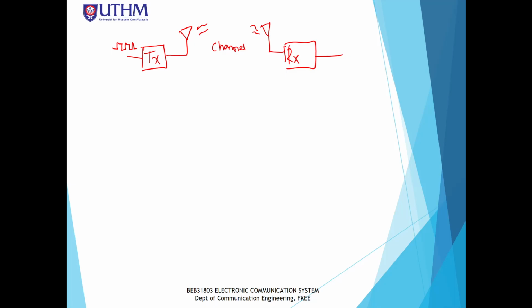So what we do is modulate with an analog carrier. The analog carrier is modulated with the digital input data. This modulation will change the amplitude characteristic of the carrier in accordance with the digital input variation.